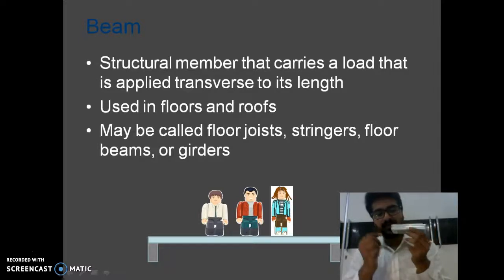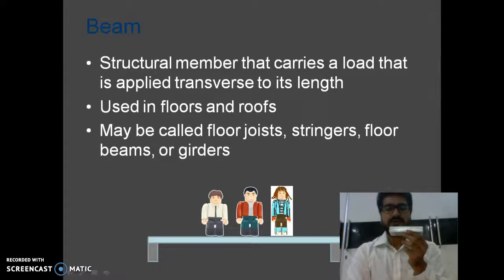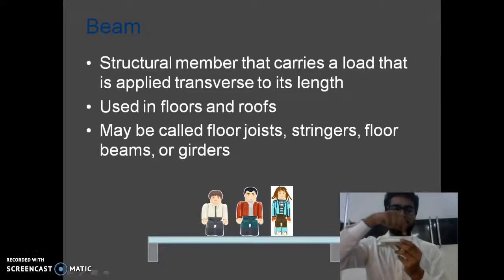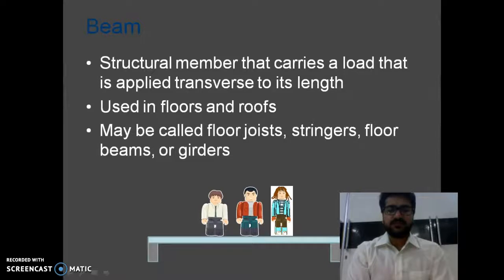So basically, an axis which will be passing through the centroid of this plane will be called the longitudinal axis, and the axis perpendicular to this axis will be referred to as the transverse axis. So it is a structural member that carries a load that is applied transverse to its length, or perpendicular to its longitudinal direction. As we all know, beams are generally used in floors and roofs, and sometimes called floor joists, stringers,